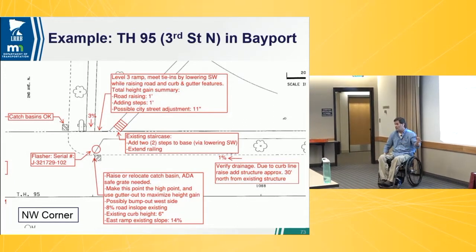So I might reconstruct this shoulder as I move that catch basin out of the way, lift that flow line 6 inches. So I'm almost there, but that's where that last 2.5 inch blister was. I'm going to pave the main lines 2.5 inches higher. So I can raise this road, say 8.5 inches. I can lower the landing a foot, and there we go. So I mean, if you really want it to happen, you can do it.